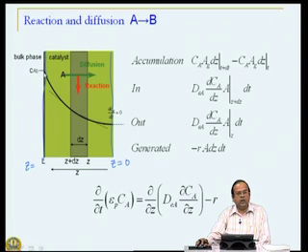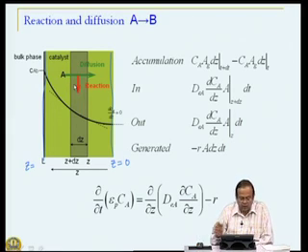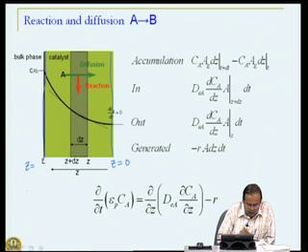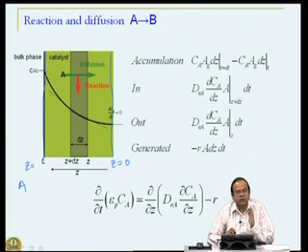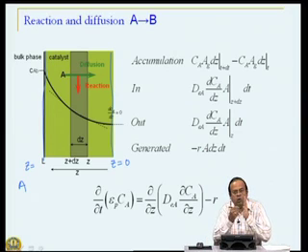So, the concentration at this point is the bulk concentration C_AB, and concentration will decrease gradually as material moves through this porous catalyst. What is responsible for movement of this material? There is diffusion, but along with diffusion there is a reaction also. So, we will have to account for all these processes. So, let us define few terms. For example, our cross sectional area, that is area perpendicular to the flow, is let us say A.